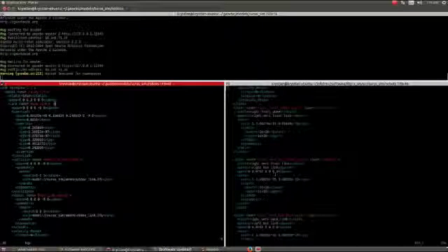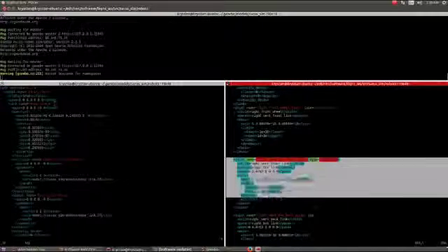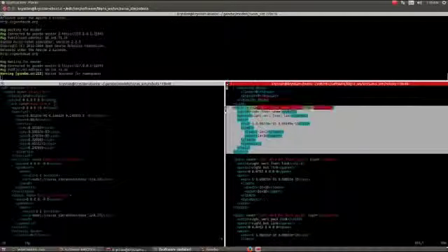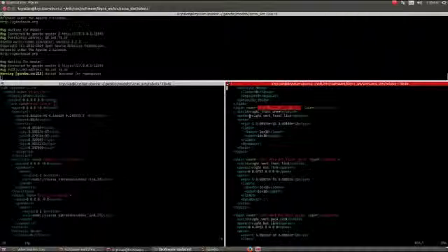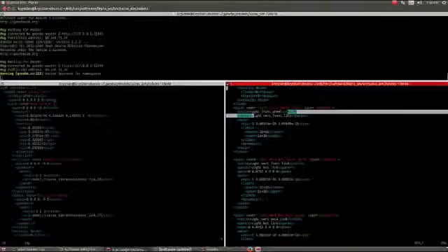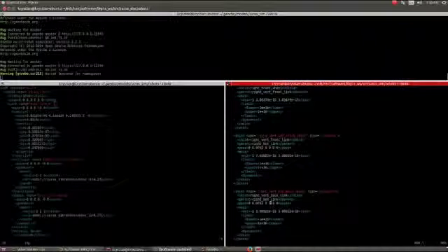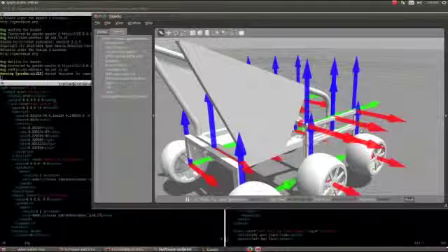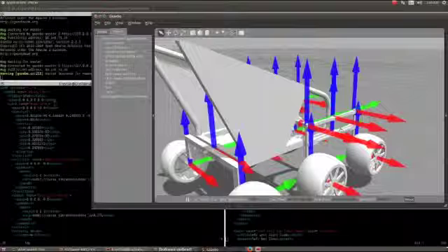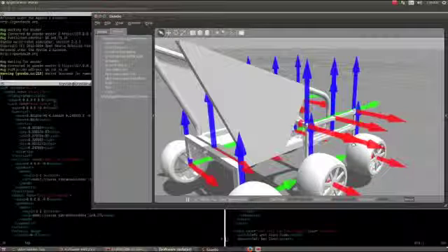For the joints that we need, just as a reminder, we need the two bottom joints. This would be the robot's right linkage, the front vertical link with the bottom link. On the right of the robot, we have the right bottom front joint, and that's going to take care of the joint right here. The child is going to be the right vertical front linkage, which is this one here, and the parent link is going to be this bottom link right here.